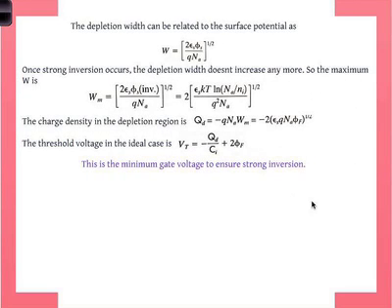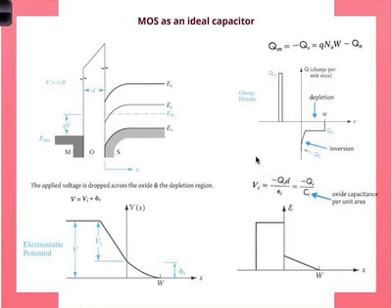Okay, now we can mathematically relate the oxide capacitance to the applied voltage. So first of all, the first thing we should expect is that the capacitance will be voltage dependent, right? Because if you think about it, the charges here on this side are clearly voltage dependent. If I apply more voltage, I can make it more inverted, so I can create more charges here, right? If I apply more drain voltage, I can increase the depletion width, so I have more charges there. So clearly the capacitance, or the capacity to store charge, will be voltage dependent.